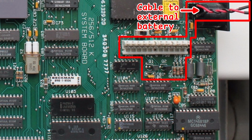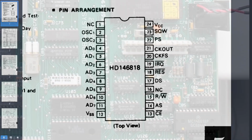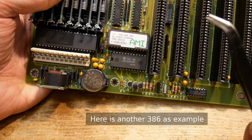That's why we need the third part of the circuit, the battery power supply, which is made up of a couple of resistors, diodes, caps and 2 transistors. This power supply not only keeps the oscillation running when the main power is off, but also powers the RTC chip on pin 24, which is specified for voltages between 0.3 volts and 7 volts. So theoretically, this whole setup should run even if the battery charge is very low. That's why those circuits could run with the same battery for 10 years or more. So this was a brief overview of the first RTC circuit implementation as you could find it on most 286, 386 and even some early 486 PCs.